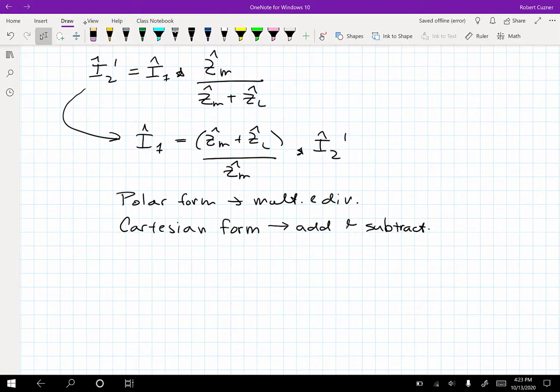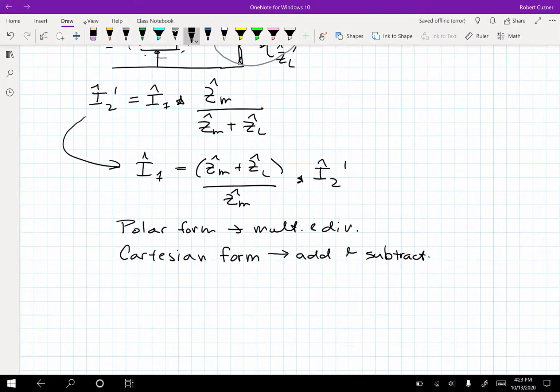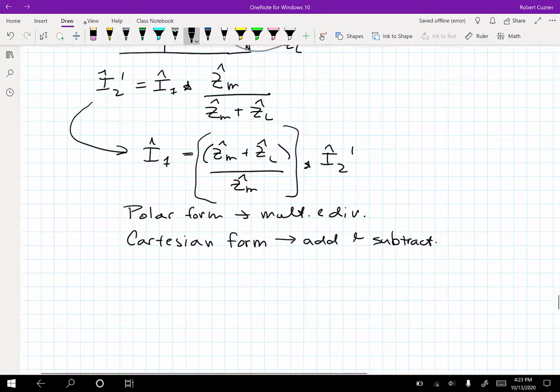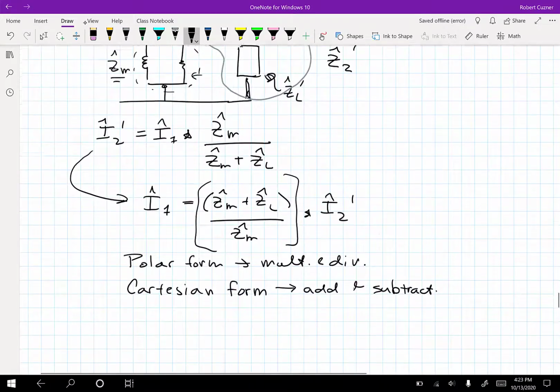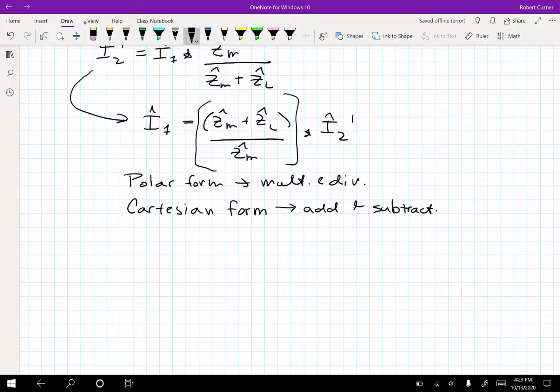Okay, so that would tell me that I'm going to probably want to have these impedances I'm interested in here. Before I'm done, I'm going to be doing some additions and some multiplications. So we can find ZM. It's the parallel combination of these two branches of impedances, RC and XM.